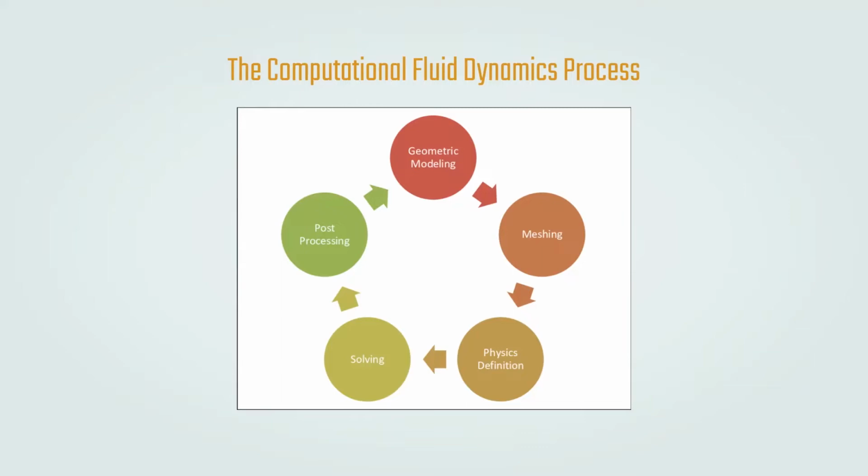define the physics that we want to apply in our fluid flow case. We can either apply gravity or no gravity. We can apply what sort of turbulence model that we want to use. We can apply the boundary conditions here, the viscosity, etc. And then after that, of course, it solves the Navier-Stokes equation based on the boundary conditions which have been prescribed.